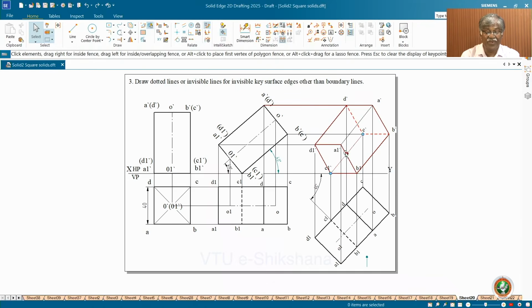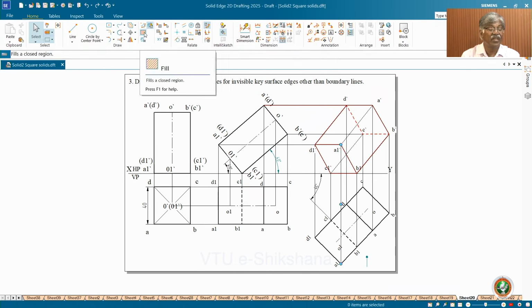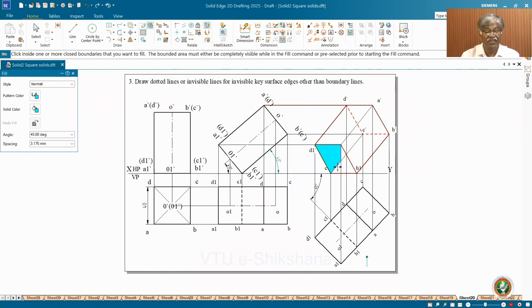Then you come to this point, this line, very interesting. CC1 is actually dotted because of bends. This is dotted, this is dotted, this is also dotted, invisible bends. Or crossing line. Already a dark line is there, you cannot have another dark line. Or fundamental concept, this is visible surface. Okay, so I can explain this. See, this is visible key surface. You cannot have again dark.